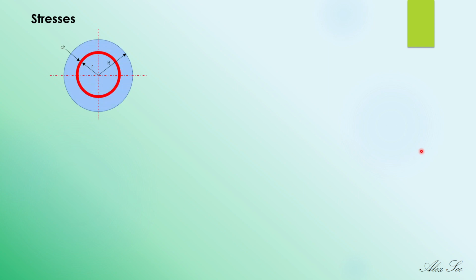So let's say this is the cross-sectional surface of the shaft, and let us consider one tiny element, an elementary ring with a thickness of dr, with a radius of r for the internal and r for the external, the total radius. So the shaft cross section.